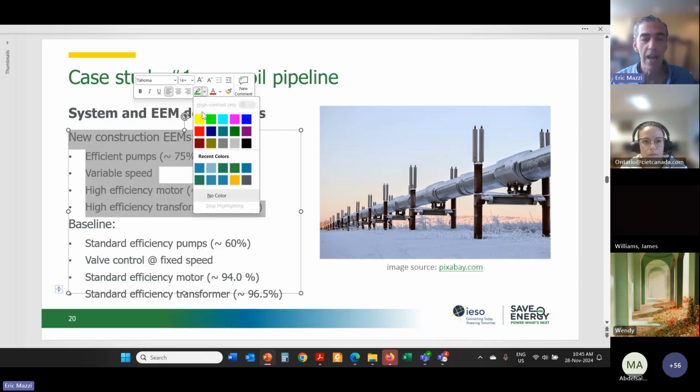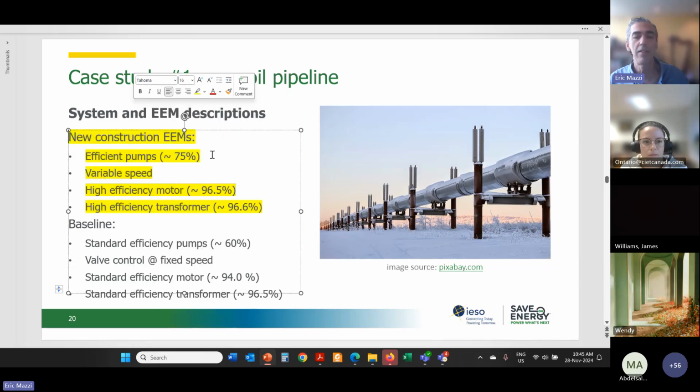built a model of the as-built system with these efficiencies in it. I mean, these are made up, they're approximate, but they're very, with the variable speed control, the actual pump curves, the actual motor efficiency data that you get from manufacturer and transformer. So a model was built of the system as it was built at the actual production rate and product mix. And that model was calibrated to match the metered consumption of the pumps and the pump motors. So that's the first step in option D.